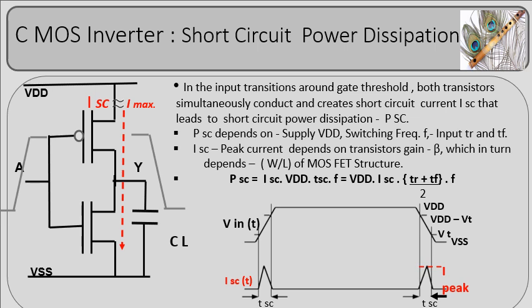During this period, the NMOS, being a fast device, switches on faster. During this transition, for a very short period, both transistors are in conduction state and conduct current, resulting in short-circuit power dissipation. Short-circuit power dissipation, in addition to slow input rise and fall transition, depends on increased power supply voltage, capacitive load, and threshold voltage of the transistors.